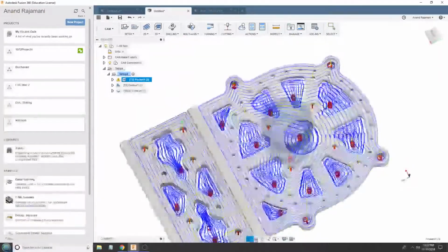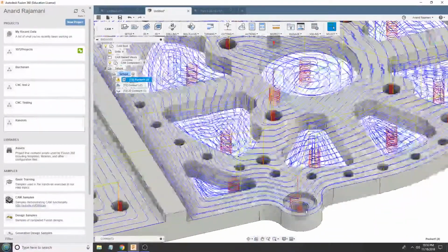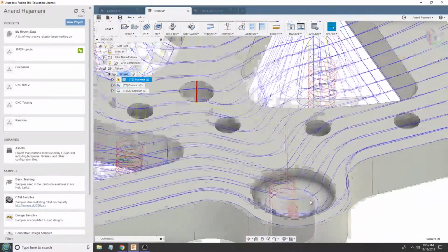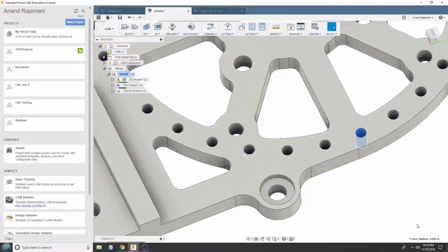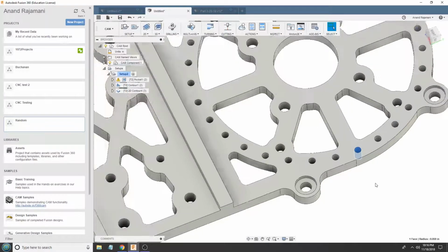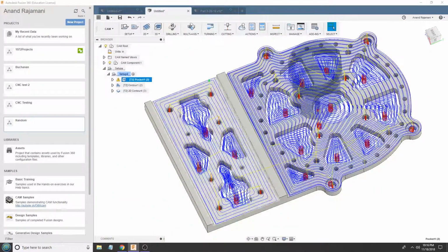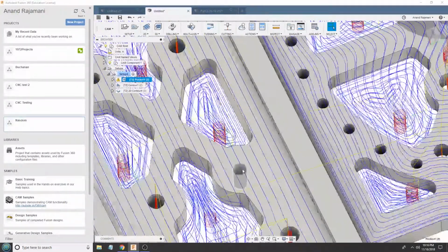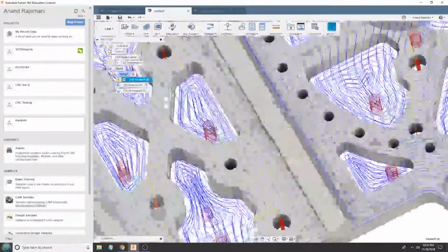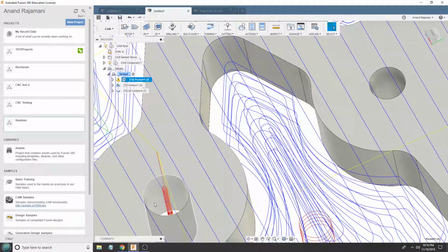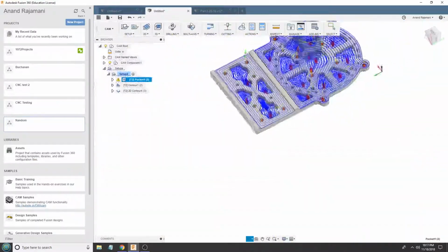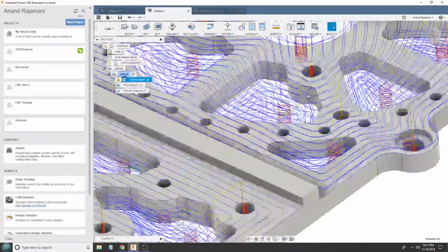And you can see that it's a really funky looking toolpath, but you can actually see it does do the counterbore there. It doesn't get into all these holes, but the reason for that is that these are tiny holes that are smaller than the end mill. They're less than an 1/8 inch, so of course it's not going to get in there. This hole is also less than an 1/8 inch. This one is an 8-32 tap, so 0.136. This 8-32 clearance, 0.165. So it'll get in here, but not in here. But apart from that, it's doing everything very easily.